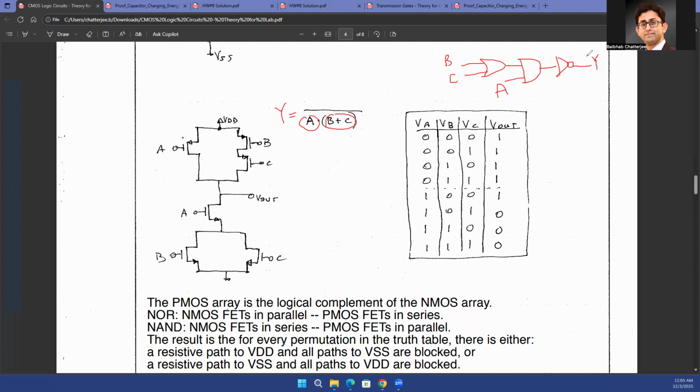Exactly. So NAND gate is a universal gate, NOR gate is a universal gate. So you can use De Morgan's theorem and convert them into universal gates, right? But now you have asked a very, very important question: what's the advantage of this? Remember that on the right-hand side, this is perfectly fine. You have implemented a digital logic, but you have used one OR gate, one AND gate, and one inverter.